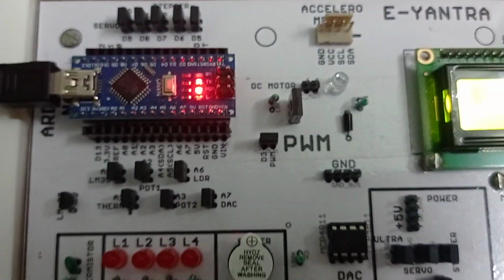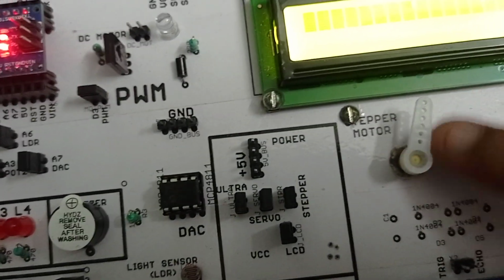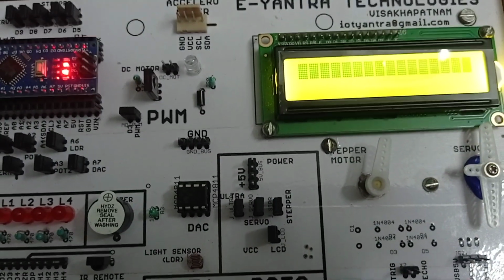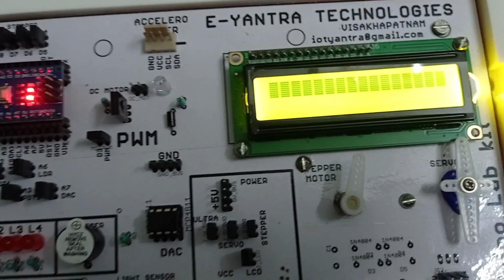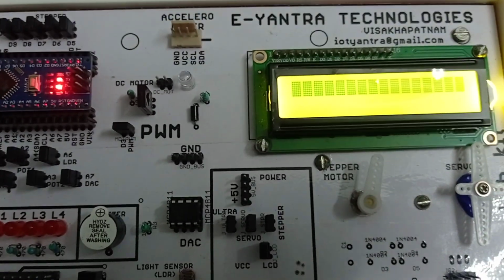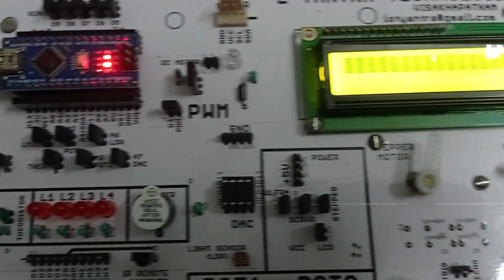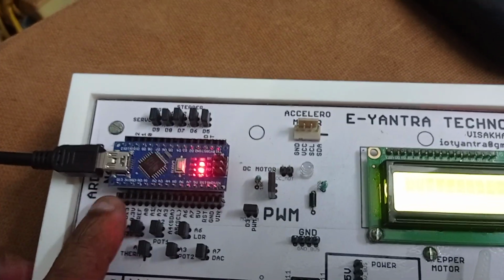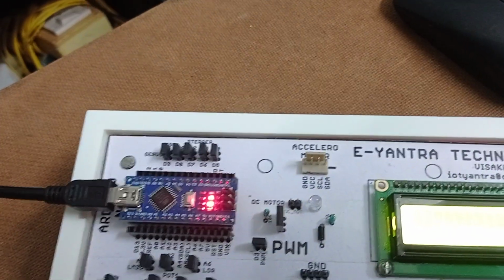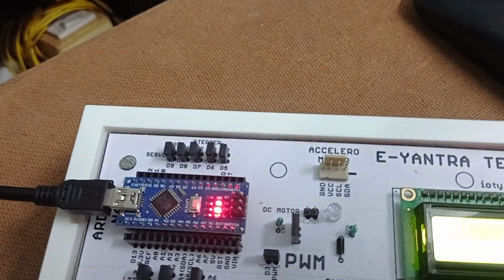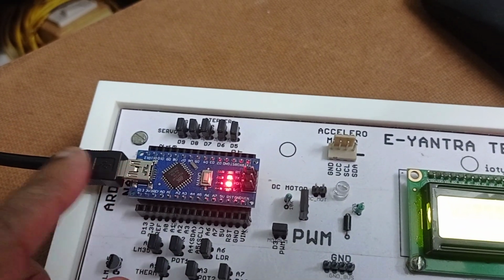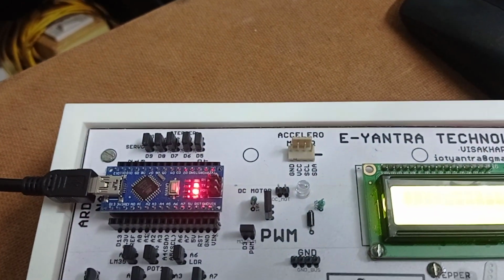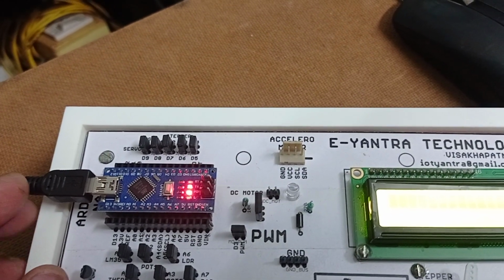Because you cannot run this stepper motor directly. See here, there is a wing attached to see whether it is rotating or not. This stepper motor comes with a current rating of about 200 to 300 milliamperes per coil. So it is going to draw that much high current, as a result of which Arduino cannot deliver this much current. Arduino can hardly deliver a current of 20 to 30 milliamperes per pin. Hardly 20 milliamperes you get. That is also not safe. So how to get this much current? Actually, it is powered by USB. Our USB port is capable of delivering up to 500 milliamps. Any standard USB port on any computer can deliver up to 500 milliamps.